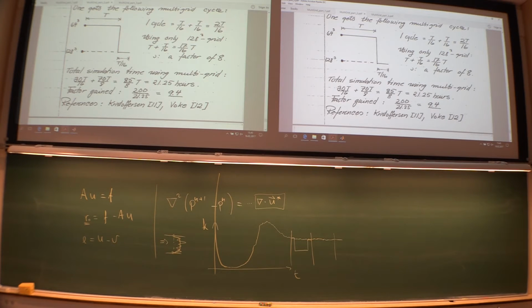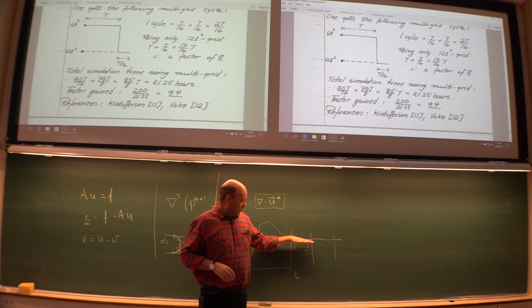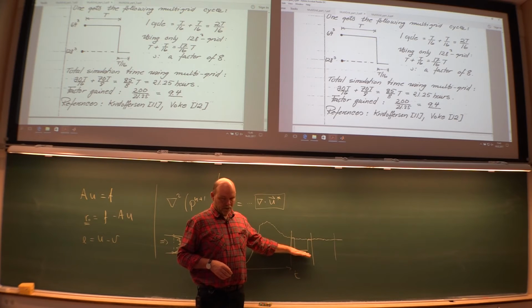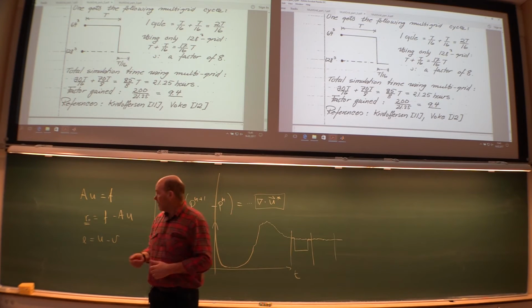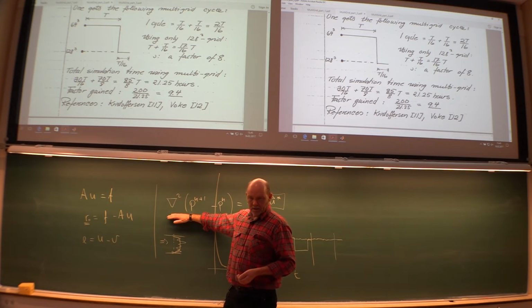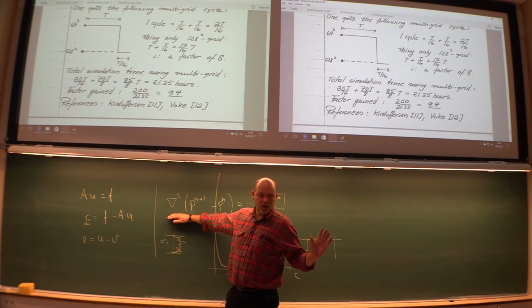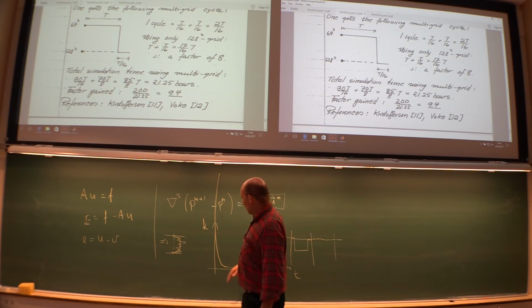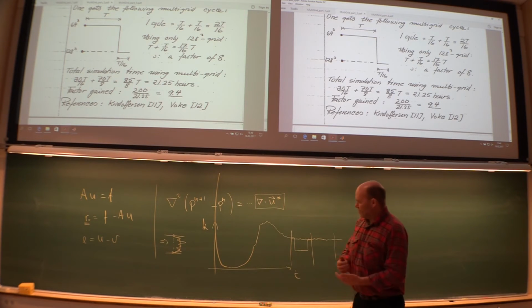And now you are not talking real multigrid. Fair enough, I had 2 different grid levels, the fine and the coarse, but nothing more. I didn't take my Poisson equation or something like that. I took the full, entire Navier-Stokes, everything, and just solved it on a coarser mesh system. So that's actually not the way we think in terms of multigrid.